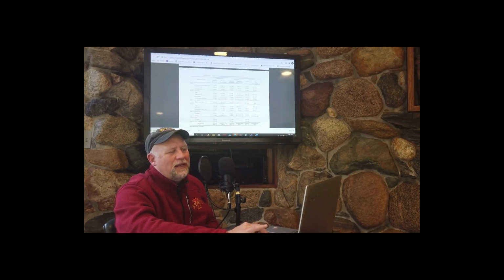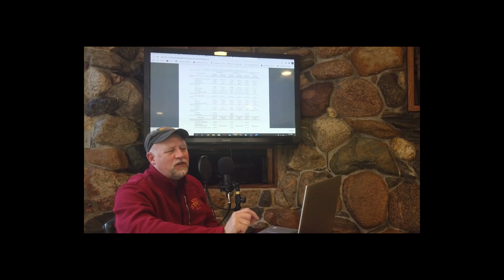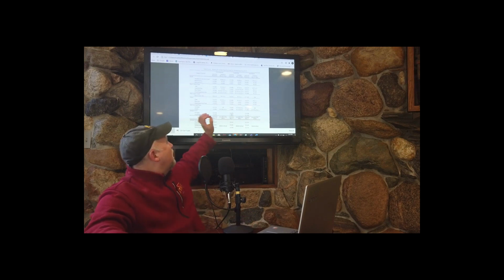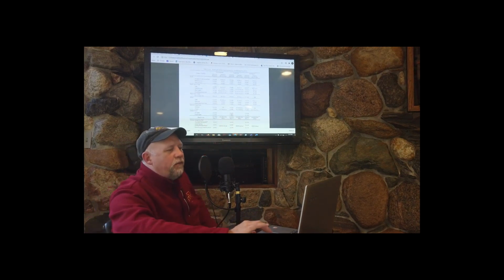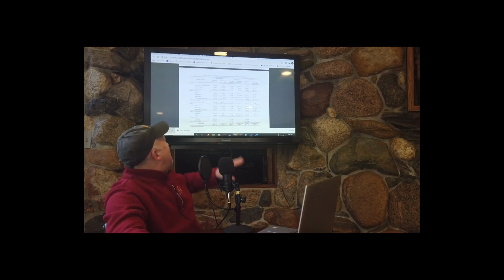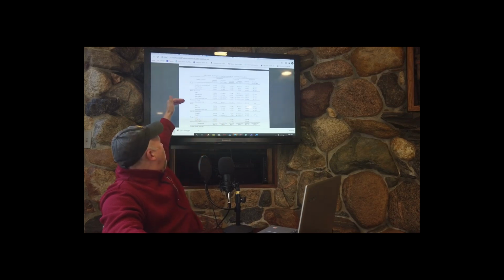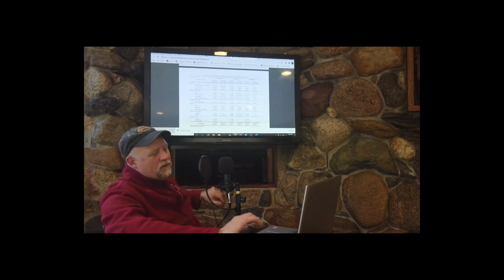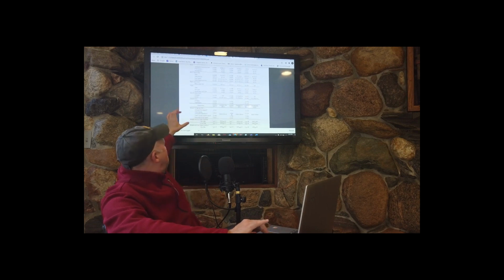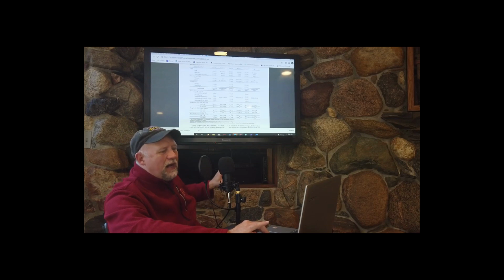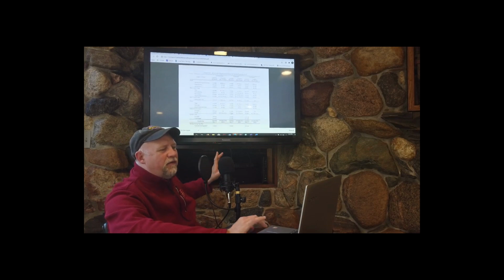So then what I did is I printed out table 5.5-5. So this is for climate zone 5. So what this tells us is if I need to know what is the minimum energy performance level for a wall, a floor, glazing, doors, skylights, I can look at this table and find out.